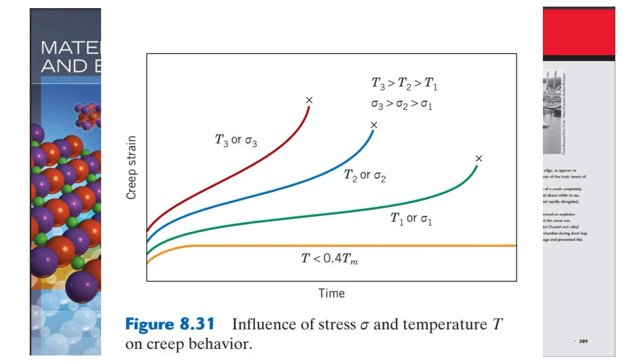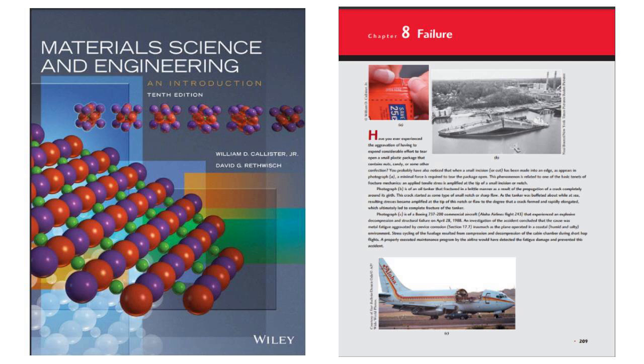and it shows how the time to rupture, like how long it takes for it to actually break, decreases dramatically as the temperature goes up. Absolutely. Heat is a big factor in really accelerating that creep process. That's why jet engines and power plants, things that operate at very high temperatures, have to consider creep very carefully. You have to make sure that your materials can withstand those extreme conditions.